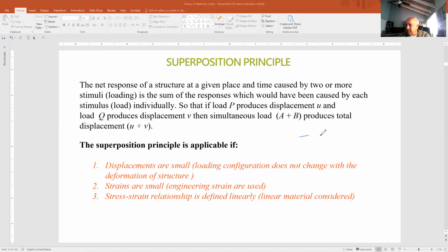Consider the case of buckling. If I have a beam, you learned it before, and I apply the compressive force here, as long as the load is small, I have only compressive stress developed here, sigma equal to P over A, where A is the cross-section of this part. But as P is increasing, the beam at some moment will buckle, so it assumes a new shape.